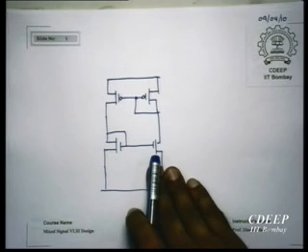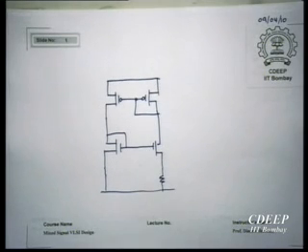If there is no R, then because there is a current mirror feeding the current mirror, once you start it up at some current, it's a self-sustaining circuit. It can stay at any old current, it is happy keeping the current. It's a current keeper circuit, just like a flip-flop is a voltage keeper circuit. You give it 0, it remains at 0, give it 1, it remains at 1. Here you start it off at some current and it remains at that. That is where we have a bit of a problem, because what is the likely value of current that this circuit is going to start at? 0. So it is happy. If both currents are 0, no current is flowing, everything is off, this circuit is not working at all, but it is happy.